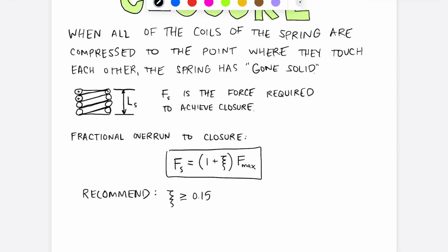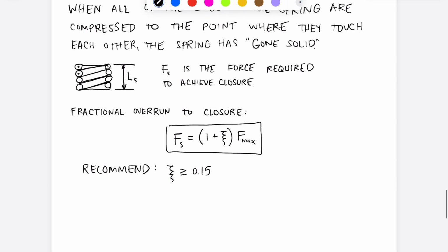And so having residual stresses when you're concerned about fatigue can be disadvantageous. So anyway, think about set removal twice, especially if you have an application with a lot of fatigue, meaning a lot of load and unload of your spring. Okay, that covers closure.